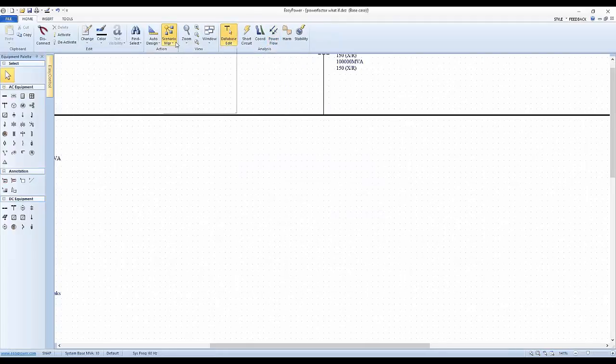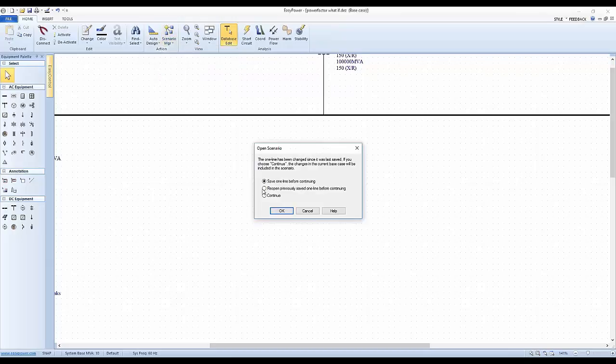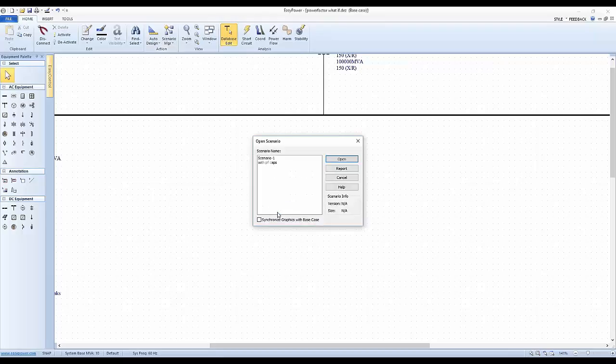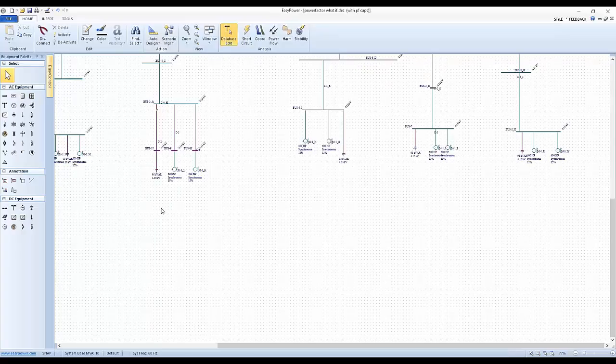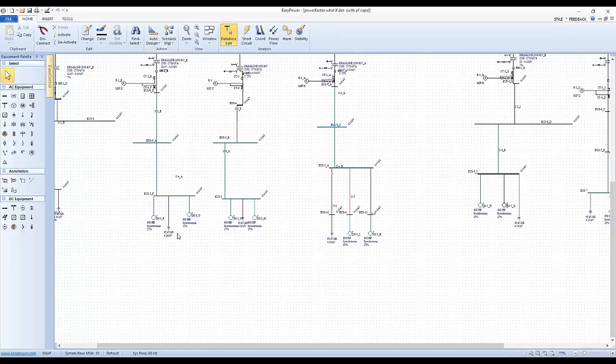Already got a scenario set up where I've added some capacitors. So now the capacitors just need to offset that reactive current we were seeing with the loads we were talking about. So let's go back and see how that looks. And again, we're just doing this on a what-if basis. So the question is, what if we wanted to offset some of this power factor demand with these inline capacitors?